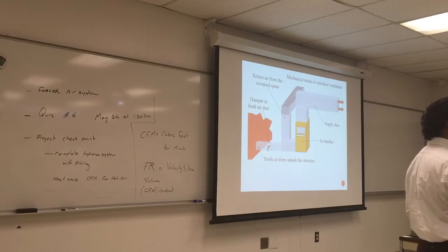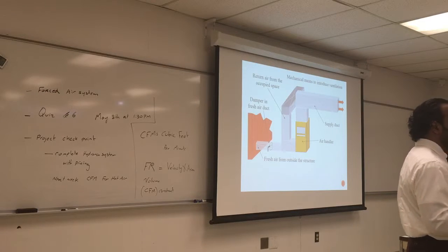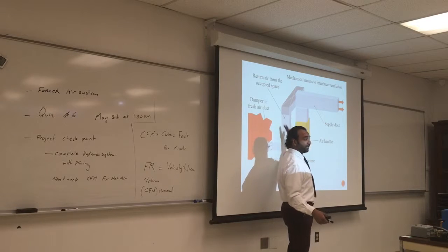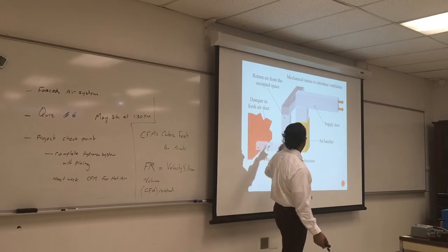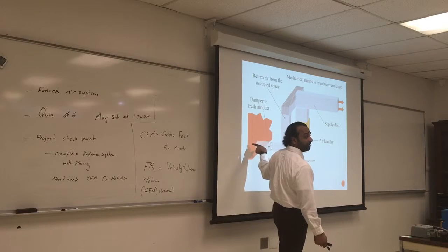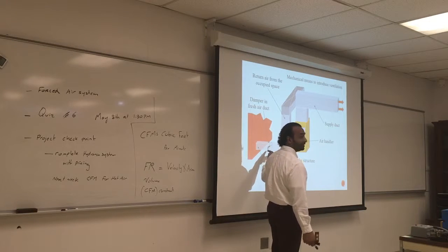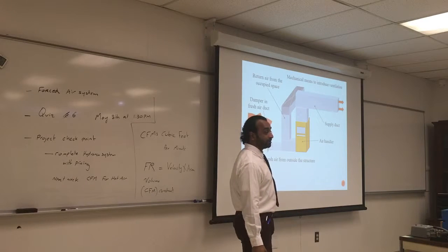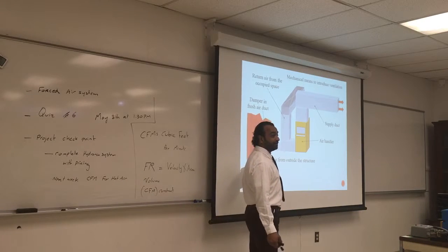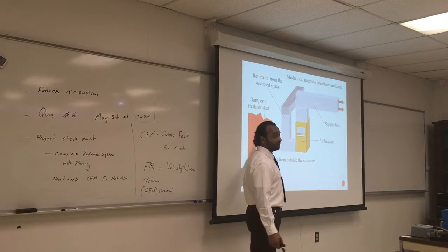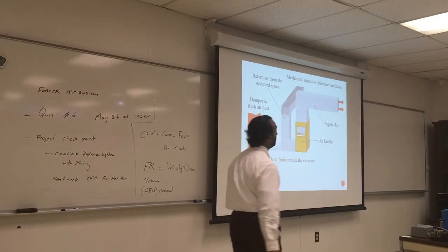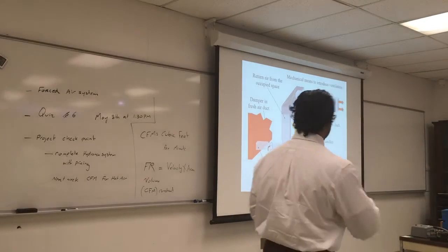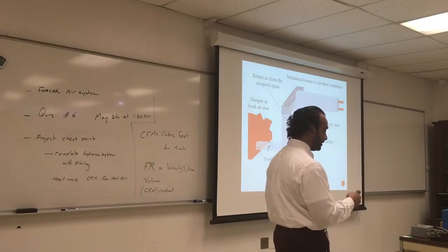So fast air from the outside produces vacuum. It's pulling things out. So if the airflow here is circulating, it's going faster, so it has lower pressure than the air outside. If you have a windy day, this should close. The faster air will have more suction. If you have a very fast wind outside, probably it will go back on the damper. Any questions? Does this make sense? Make-up air to the system means circulating the air and adding new air to the system.